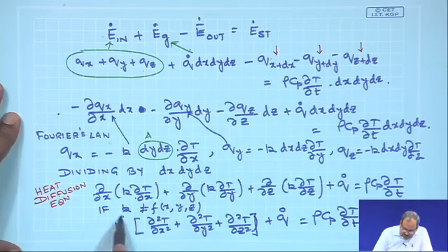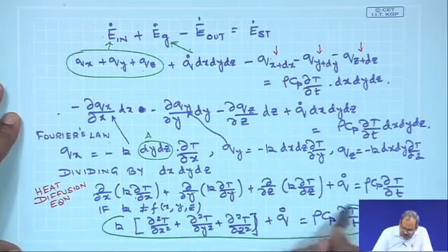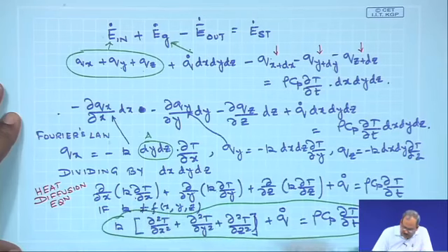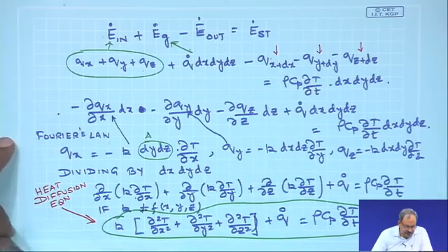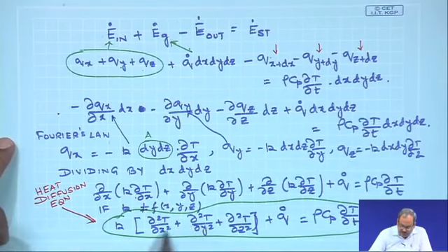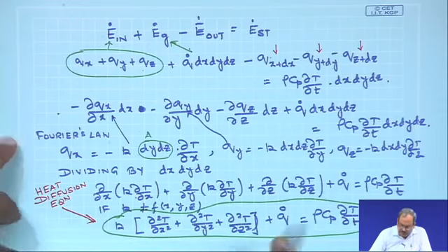So, this is probably the more common form of heat diffusion equation that you would encounter. This simply says that it is an isotropic medium, and therefore, you do not have any variation of k with either x, y or z.